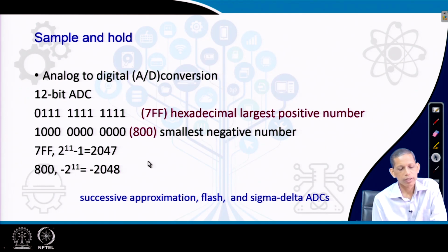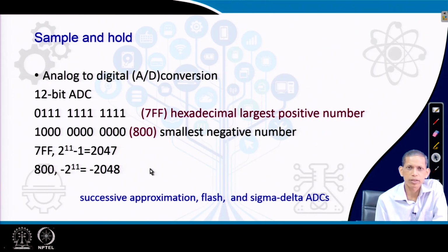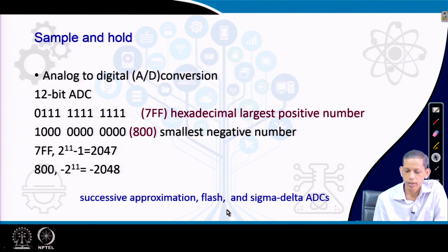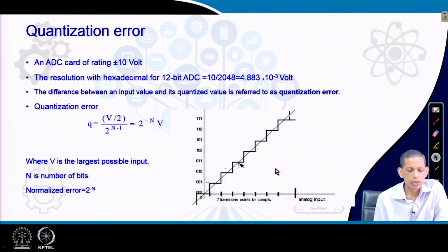So, different analog to digital conversion principles are there with the evolution of the technology. There are different ADCs available in the different relays. Earlier versions were using successive approximation, flash type is very fast, and today many relays use sigma delta ADCs also.